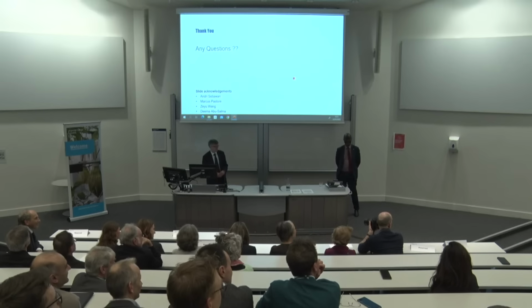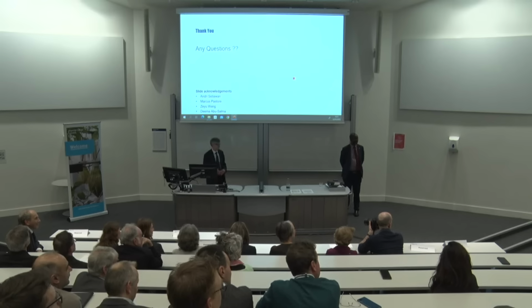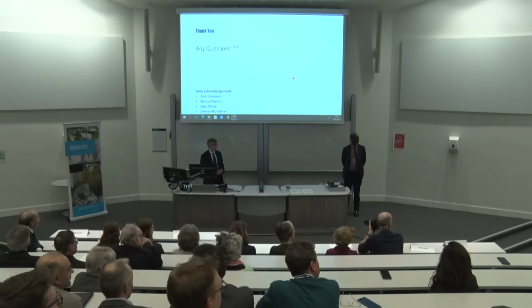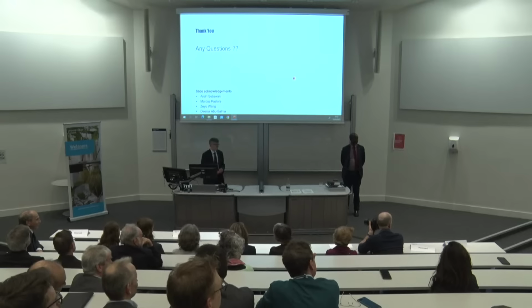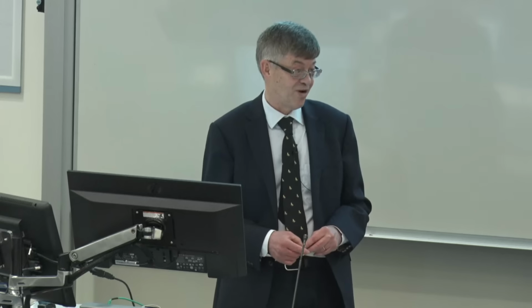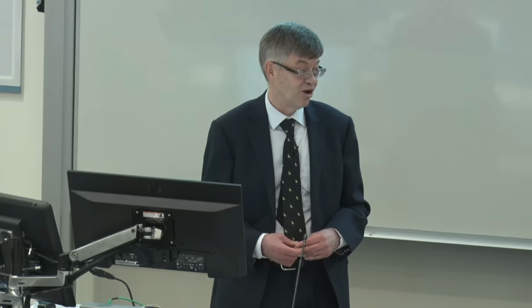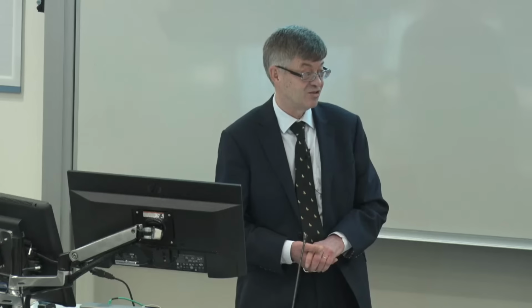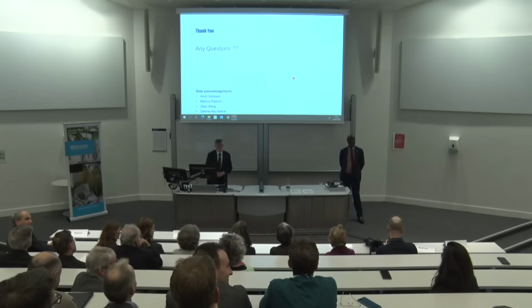Yes, there's a question from Toko asking, what is the influence of support elongation on punching resistance at internal slab column connections without shear reinforcement? Yeah, so the key thing is that the shear force concentrates around the ends of the column. So essentially, as you increase the length of the column, you get less benefit in terms of increased shear resistance than you might expect. Thank you. One more question from the audience, please, in the room.